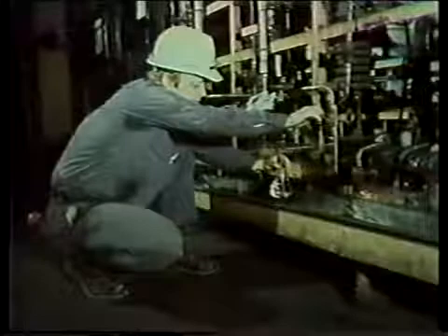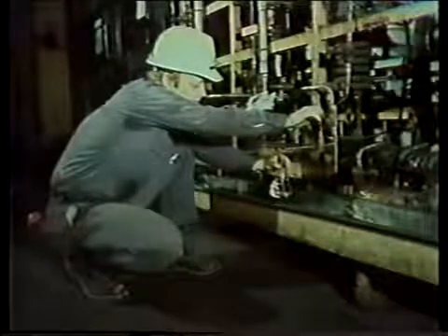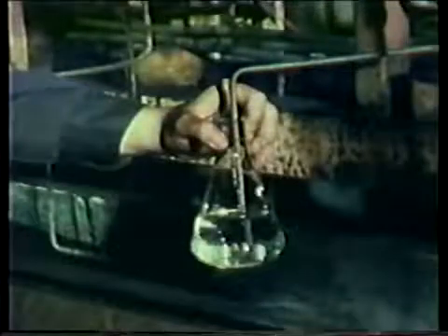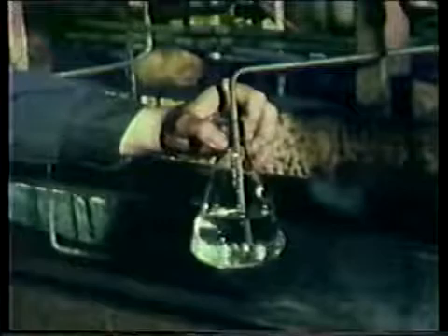This process is not as simple as it sounds. It's a very involved procedure, requiring a lot of time, equipment, and manpower. Also, if the chemicals are used incorrectly, they will attack boiler metal, and this can cause more problems than the cleaning solves. So for this reason, a chemist will regularly take samples of the chemicals in the boiler to make sure that they're not causing damage.